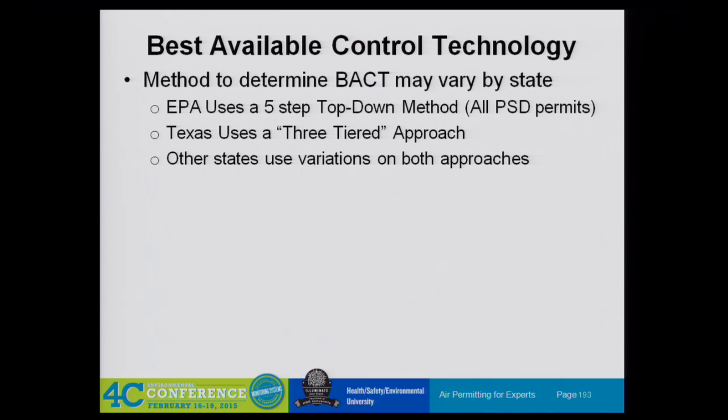The whole premise of BACT is dollars per ton control, and a lot of the agencies don't seem to get that. I've gone in numerous times and said, look, even your website, let's say for NOx, says 0.01 pound per million BTU on an annual basis. Well, they want to put a short-term limit in there too and call it that. And I'm going, okay, if you want a performance specification, we can put that in there, but it can't be 0.01, maybe 0.025 or maybe 0.015 with some extension.